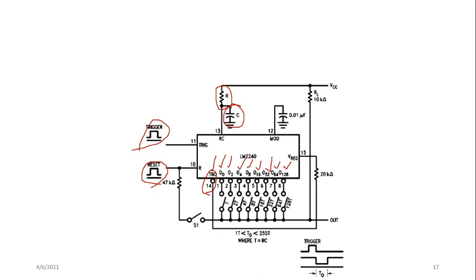If you see here, the time period of every waveform is written: T, 2T, 4T, 8T, 16T, 32T, 64T and 128T. And you are getting the time period as 1T to 255T. Remember 128T: when I say T, the on period is 128T and the off period is 127T. So overall, how much time period am I getting? 255T.